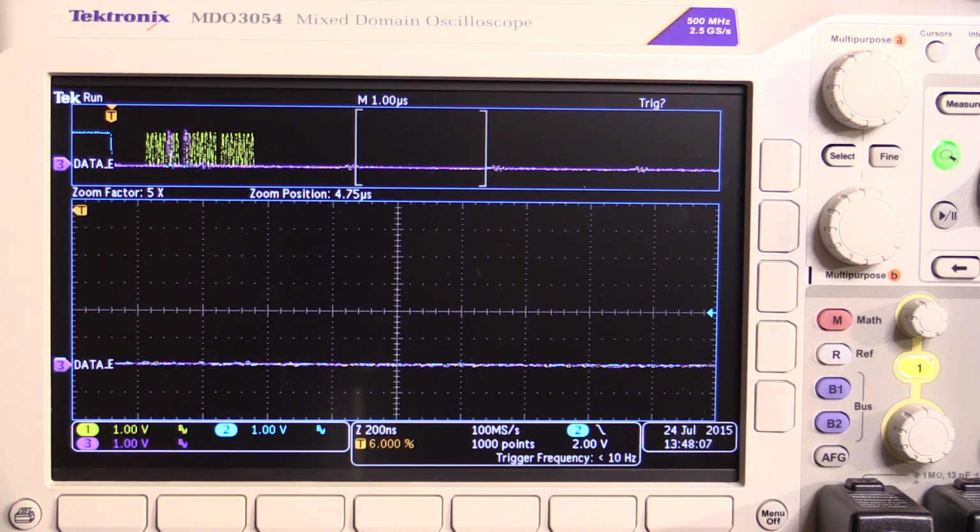But as you can see here, as far as controlling SPI devices is concerned, one of the important things is to read the data sheets and make sure you know what mode the SPI device is going to work on. I just assumed that because the previous TI devices and other devices I've been using worked happily on mode 0, this would work on mode 0 as well. And of course it didn't.